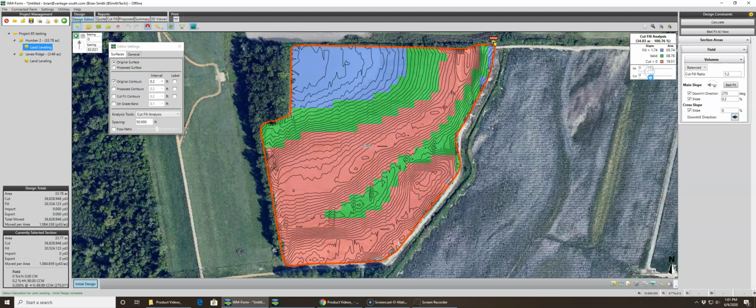Okay, we're going to do this cut, so if we put how many acres has more cut than 1 foot, so we'll put our slider at 1 foot, that's real close. And then we've got an area of cut above 1.03 of 10 acres. Okay, so we will shut this back to 0 and we'll move on.